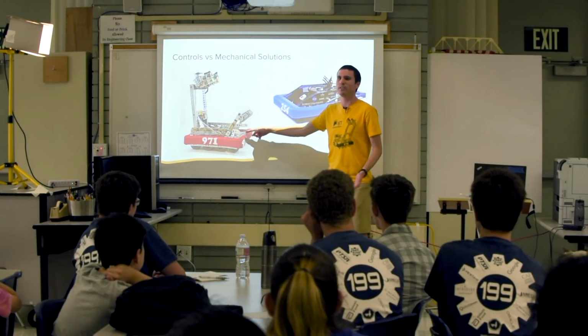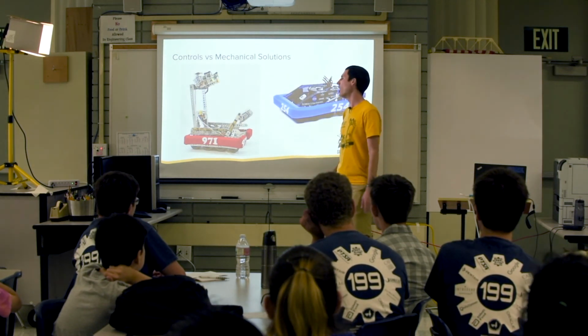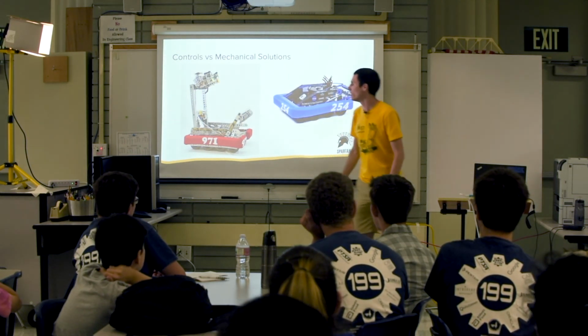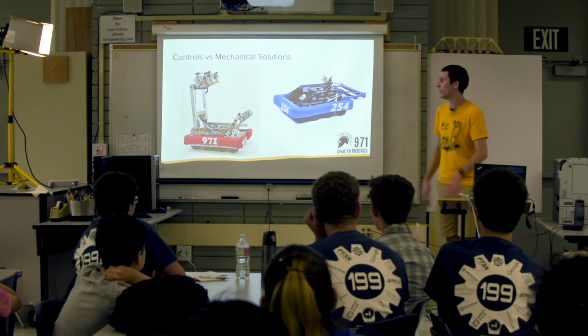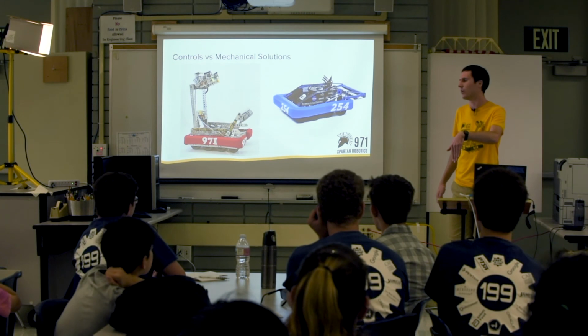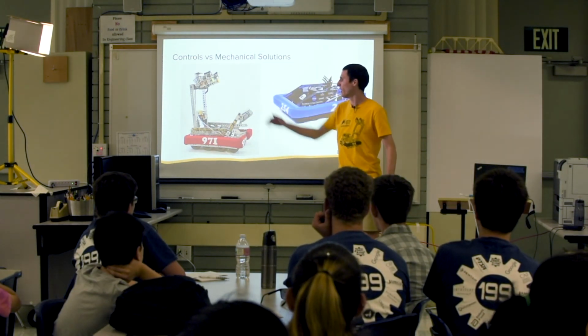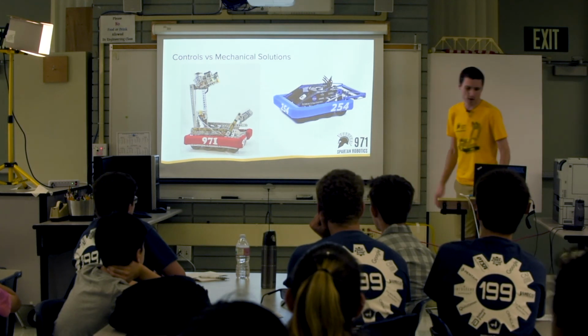It took less mechanical design, and we didn't have to think through all the integration and the packaging as much up front. And it gave us flexibility that we enjoyed using, of being able to adjust the position of the intake. I think we had different modes. When we were going under the low bar, we'd put it extra far down. When we were shooting, we held it out some. And when we were stowed, we held it back. So we took advantage of that there.